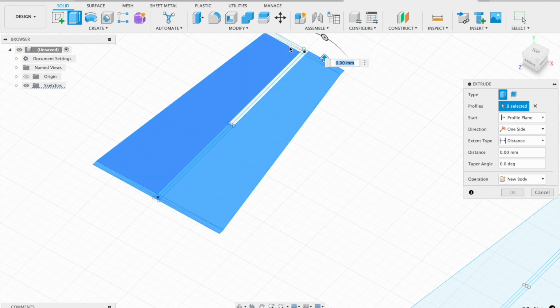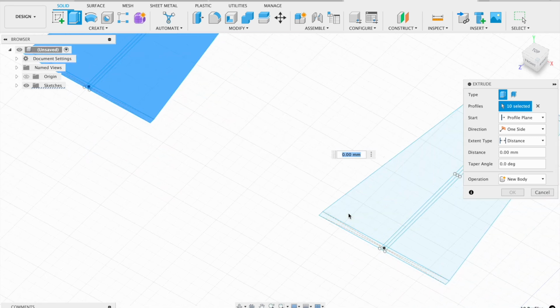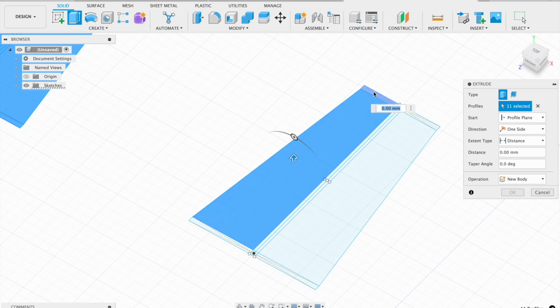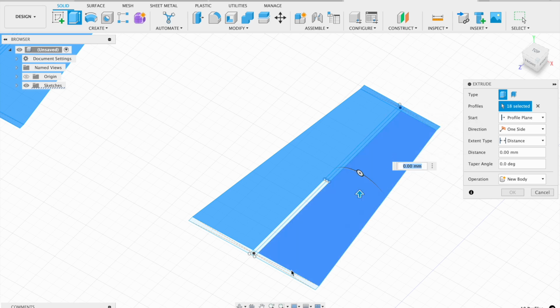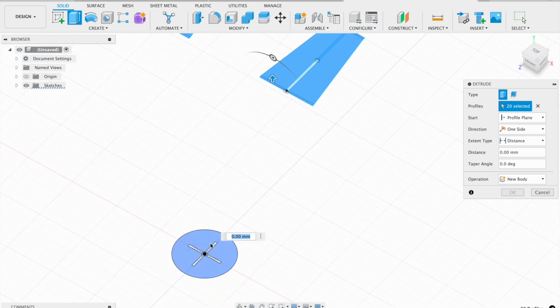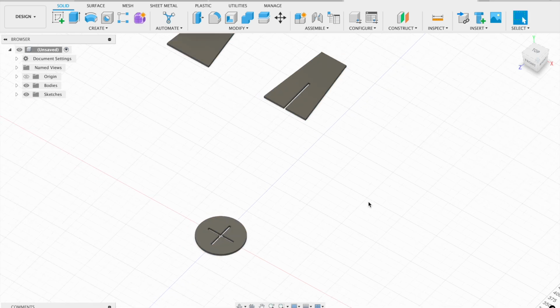So I'm going to leave a slot on the top, and then I'm going to do the same thing for this side, except I'm going to leave a slot on the bottom. And you'll see I'm selecting all of these little rectangles that are everywhere, but not the bottom rectangles. And then I'm going to select the chair also. And I'm going to extrude these up by thick so that they're extruded by 6 millimeters.